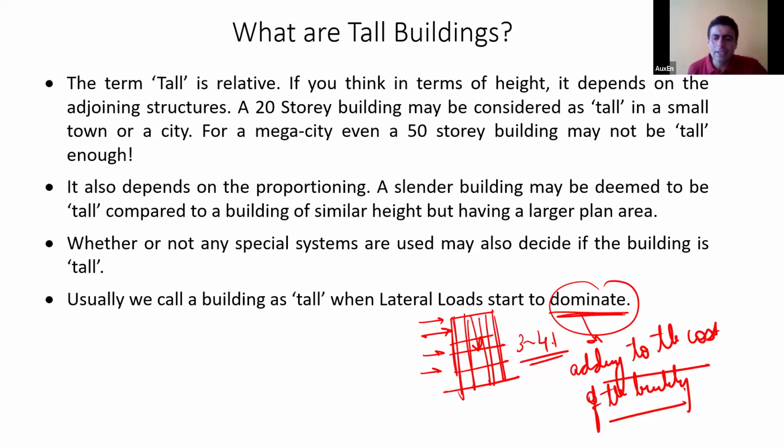So then I will not say that lateral loads are dominating as such. Yes, we are designing for lateral loads. Yes, lateral loads are adding to the overall cost of your structure, but they are not a major component of the overall cost. So when I say dominate, the design, the strength design, the serviceability design, the drifts, the deflections, the accelerations, all those have to be controlled by lateral loads. Usually then we would like to call that yes, this building is tall.